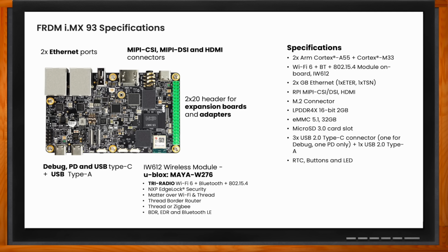There are a lot of very cool things technology-wise. One of the things that we can look at as probably the most important thing is the actual processor itself. So the i.MX 93 processor chip does contain 2 ARM Cortex A55 cores with a Cortex M33 chip as well. You can use the main Cortex A cores to run the heavier workloads, the things that you typically run in a Linux operating system. And then the Cortex M can be used for more of your MCU use cases as well. Those are kind of a cool little, 2 processors in one type thing here.